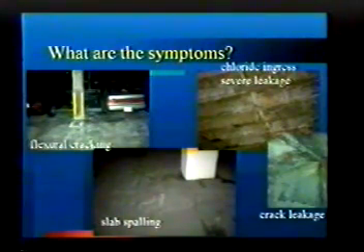All right, so let's go back to that slide. What were the symptoms? On this particular one, it happened to be from flexural cracking. The study found that the rebar was 4 inches below the surface. It wasn't up at the top. It was supposed to be designed with 3/4 inch cover. It was too far down. On this particular one, we have severe chloride ingression. This was so bad that this structure was recommended for removal.